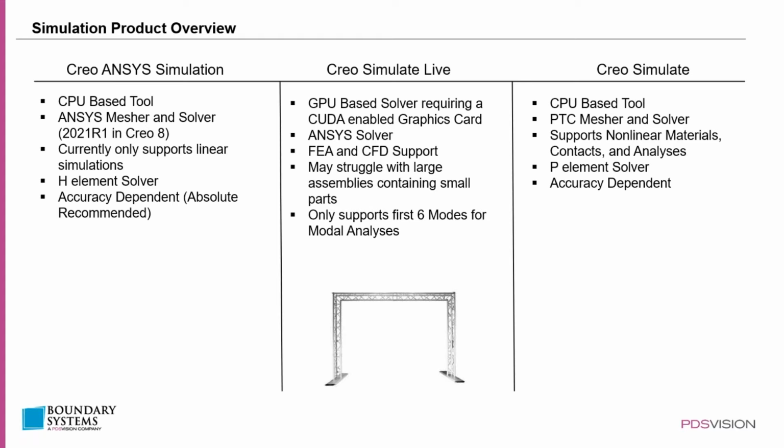Creo ANSYS Simulation is a CPU-based tool, so it does not really require any specific GPU. As of Creo 8, it's using the ANSYS Mesher and Solver, and specifically it's using the 2020 R1 Solver in Creo 8, but that is Creo version dependent. Creo ANSYS Simulation is currently only available in Creo 7.0.2 and later.